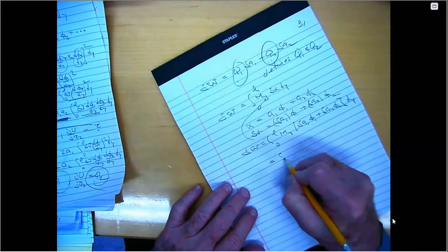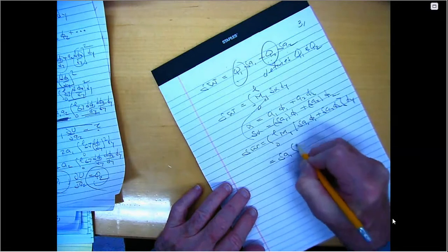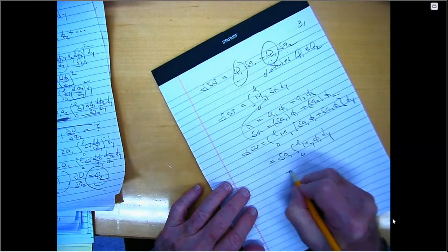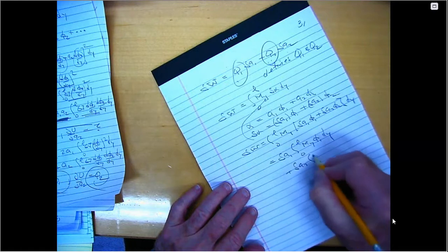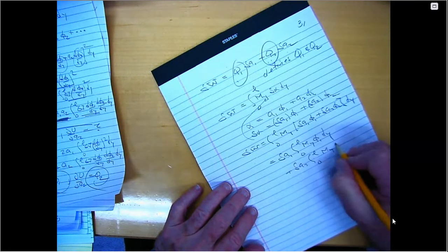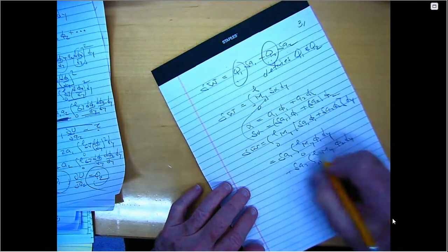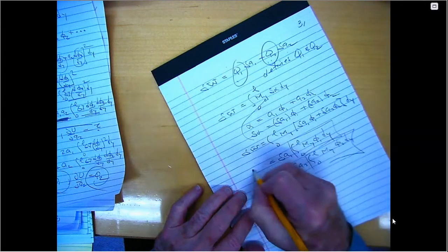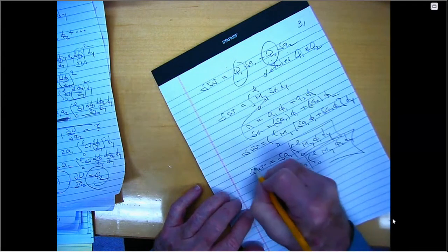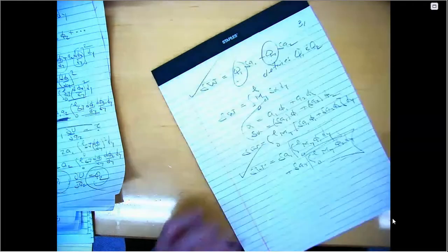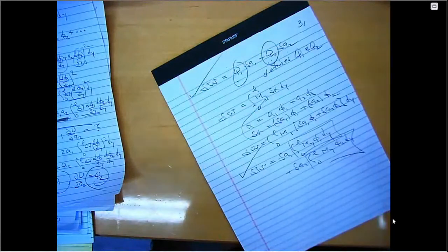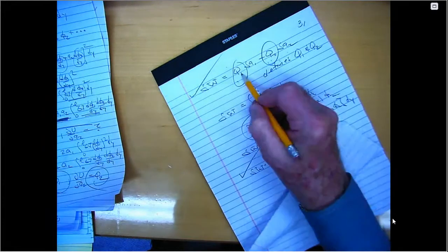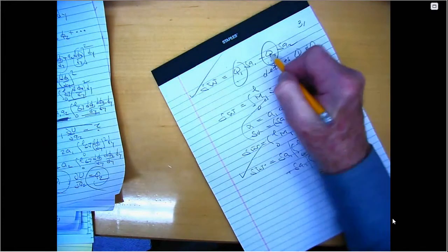This is del A1 times integral from 0 to L of m sub y phi1 dy plus del A2 times integral from 0 to L of m sub y phi2 dy, right? And I look at this expression and this expression, and I say, aha, or eureka, or whatever. This integral is Q1. This integral is Q2.